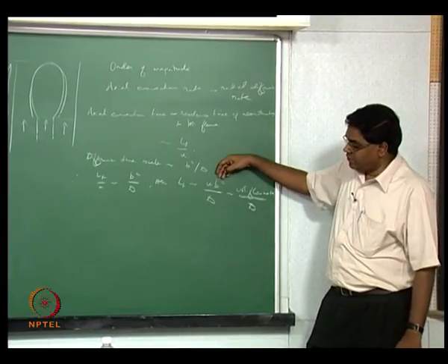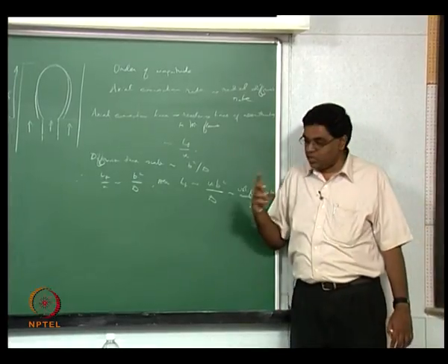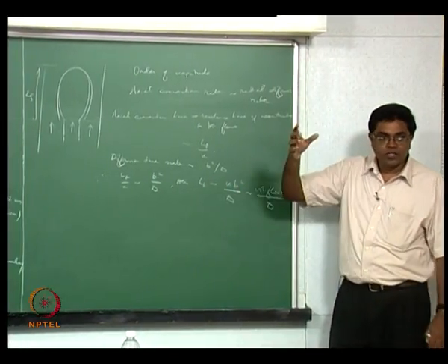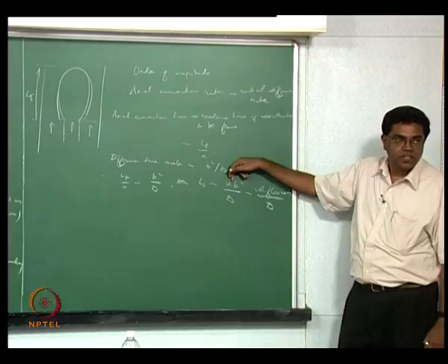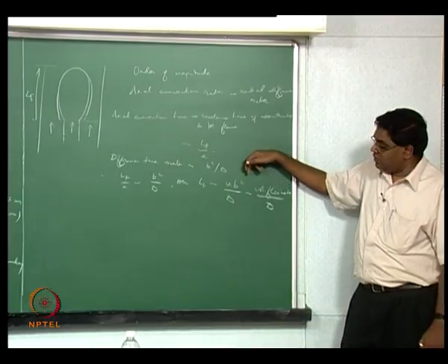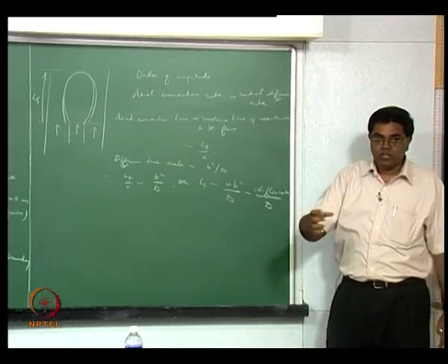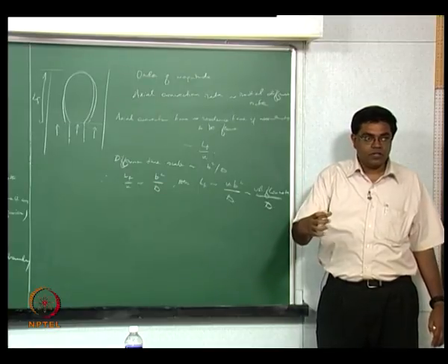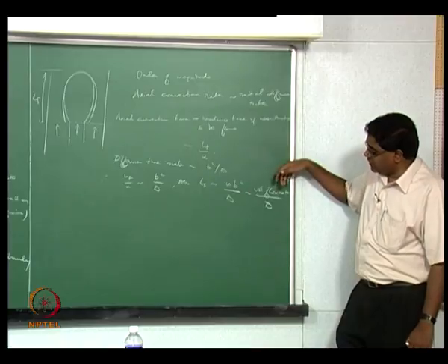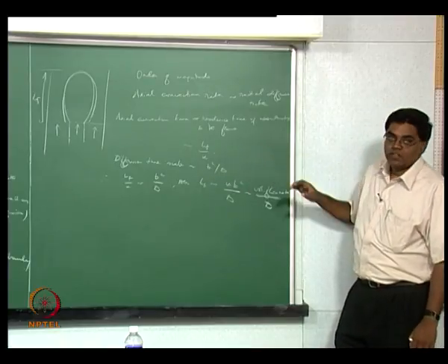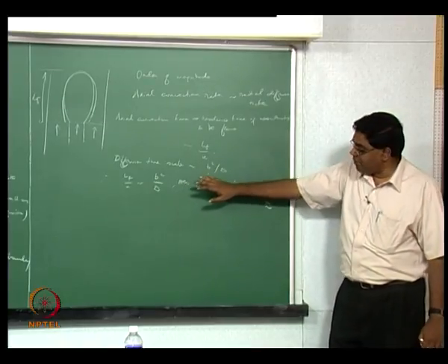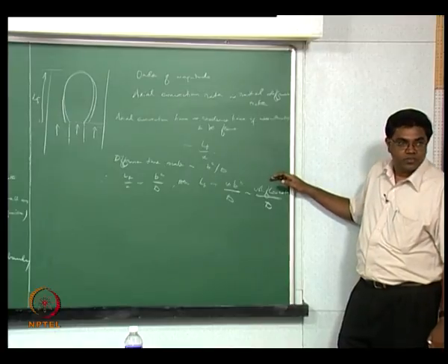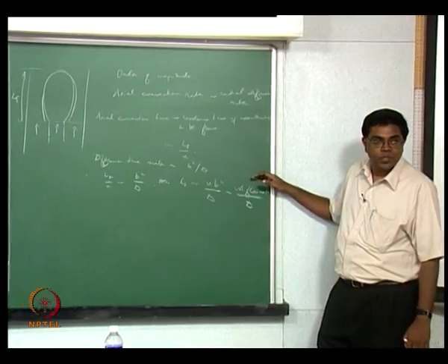If you look at it the first way, you learn two things. One, the flame height is going to be proportional to velocity and proportional to the square of the duct diameter, alright. If you look at it the second way, all you get is that the flame height is going to be proportional to the volume flow rate, alright.